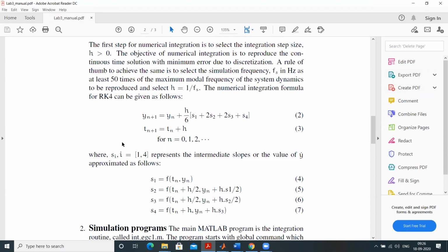No, sir. Okay. That's a bandwidth, but the control structure resonant frequency is coming from the plant dynamics when it interacts with the mounting system structure, mounting brackets and all. That is a characteristic of the plant dynamics. Normally that will be of the order of 2 to 3 times the bandwidth. That's how we design the system.